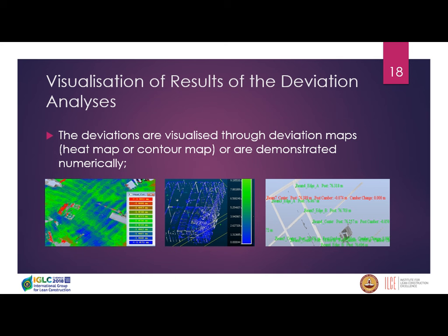It shows that the camber of those beams is changing, and it shows whether they are within tolerance or not. And we use the straightness algorithm for that. So we define a reference line under the beam, and we check how much the points are deviating from the reference line.